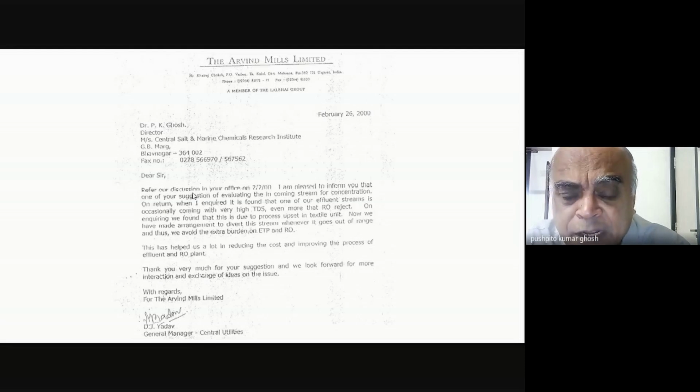You treat that as a separate entity, because after all, what am I doing? By doing RO, I'm making a concentrate stream. If the one that I'm discharging into my effluent unit is still higher than that, what's the fun? I'll just unnecessarily waste power.